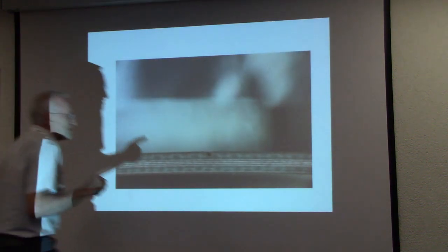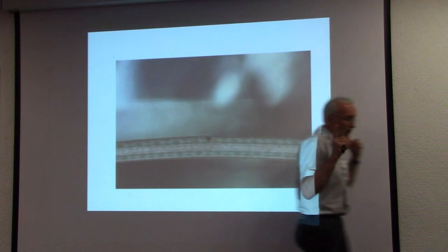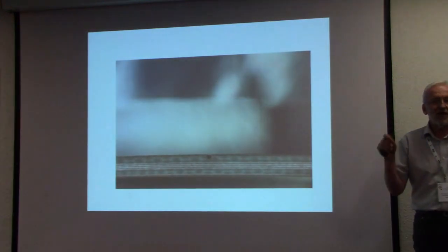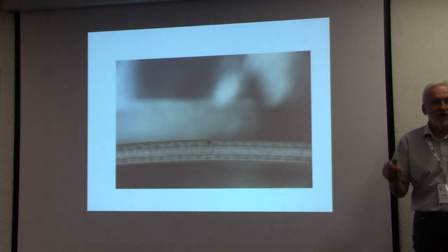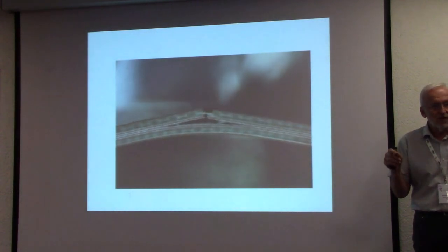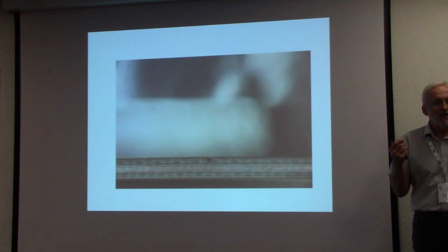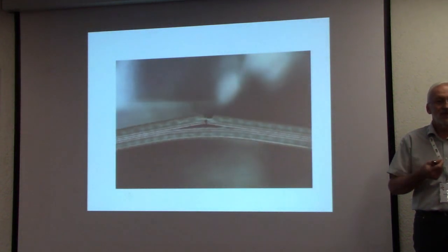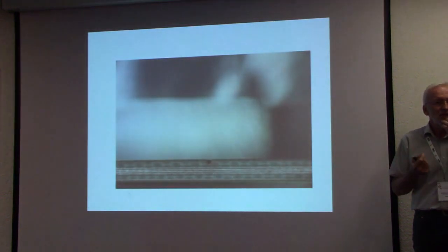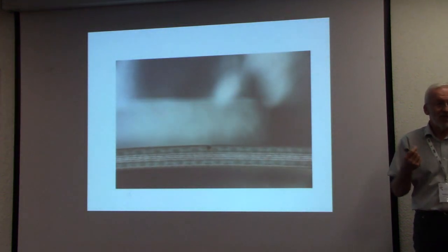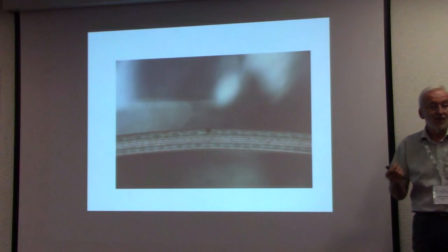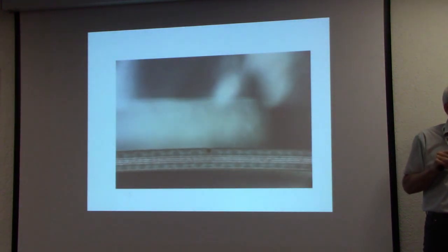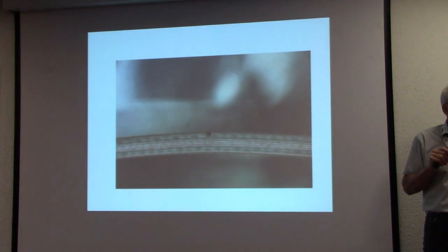All these problems, but one has to take into account that these are pure linear elastic considerations. And these are only true if it is really a pure linear elastic behavior. Otherwise, if you apply this, for example, to a plastically deformed material, and the values which you obtain are significantly above the Griffith toughness, then there is something wrong.